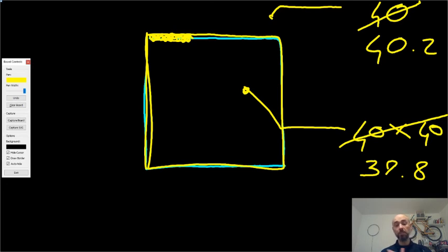Now the numbers, as I said, can change a lot based on the kind of laser and the thickness of the material itself. But in general, the rule is the same. The piece you cut away gets smaller, the hole you make gets bigger. That's always going to be the same. The fun thing is when we get to 3D printing, you see it. When you 3D print something, it is the other way around.